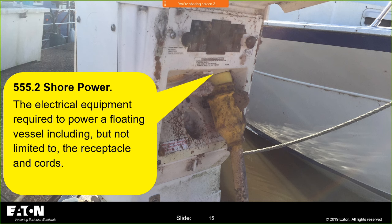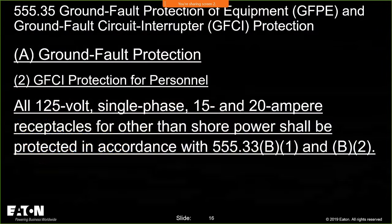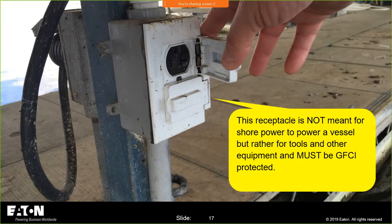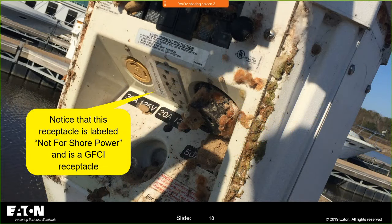And the shore power, whenever you hear shore power, that's that 30 amp outlet on that pedestal, and everything else is your receptacles. So all 125 volt single phase 15 to 20 amp receptacles have to have ground fault GFCI protection. So when you see that word GFCI, there's your GFCI. And again, it's not meant for shore power. And actually, that picture that you're looking at right there is an illegal installation. You're not allowed to do that anymore. Or depending on where you're at, you could put a receptacle out there, but depending on what it's being used for. So there you notice this receptacle has a label, not for shore power.